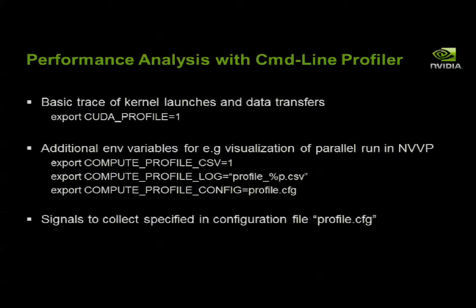But yeah, debugging CUDA applications can be a bit tricky, but that's what it is. Yeah, Ole spent quite some time on trying that for a very simple kernel, but there was this very subtle race condition that took a lot of time to isolate.